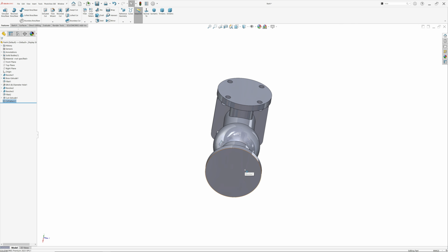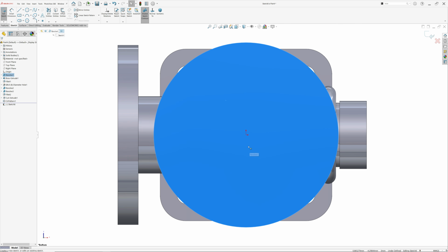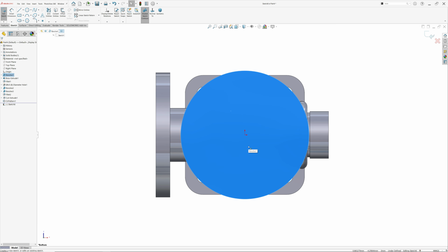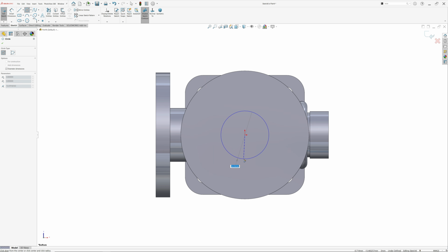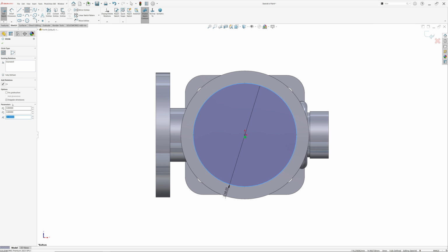Similarly, let's do this for this sketch. Activate circle 58, enter. Select for construction, activate center line, and hole should be here somewhere.